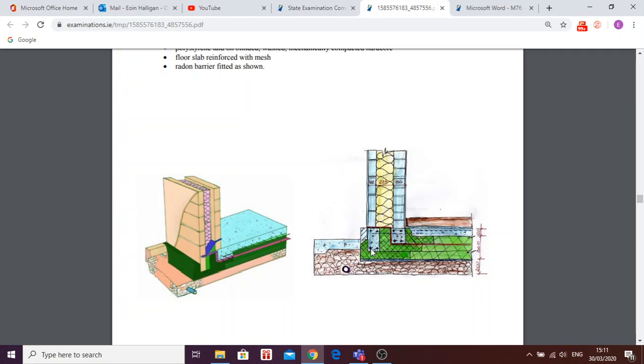So your reinforcing irons are inserted here, and this blue section here, your footings, they're poured concrete. Okay, those are your rising walls. Now, as you can see, there is nowhere for heat to escape here. If you follow my cursor, this might be a direction where heat would have been able to get out through the blocks and down into the foundation and down into the soil. This is not possible anymore because your foundation is essentially wrapped completely in insulation.